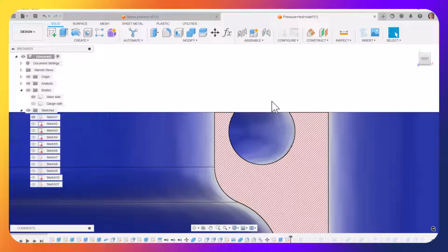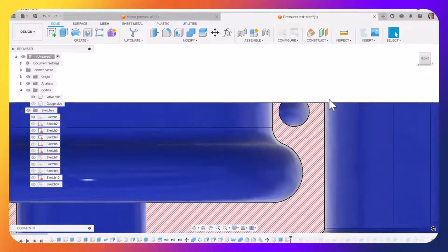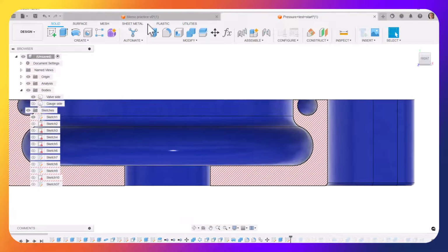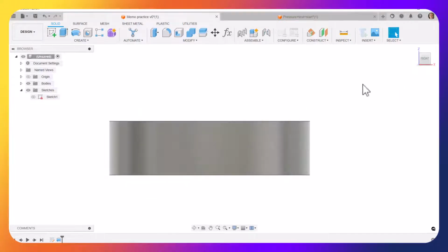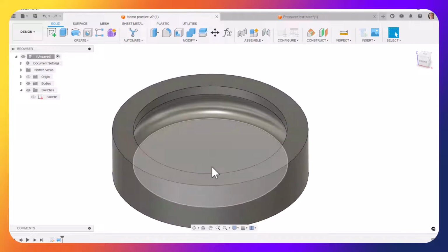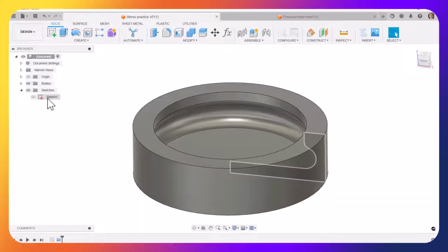I guess we could drill a hole and have a ball-shaped tool that could cut that. I would like to see though a vendor's part number for that tool to do that. I'm going to assume that we're going to instead use a ball end mill, which has a cylindrical side to it. It's only spherical or hemispherical on the bottom of it, and we'll do it that way, and we'll cut this hole. So we could add additional geometry to cut the hole and to cut that slot, but let's just see a different way of doing it.